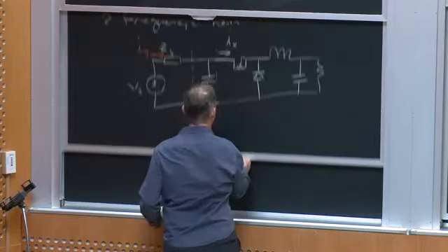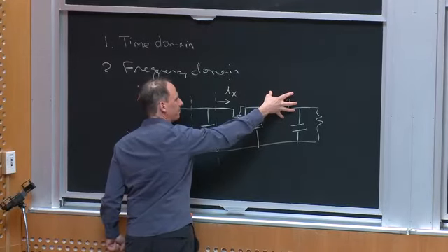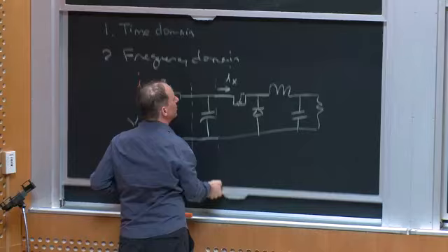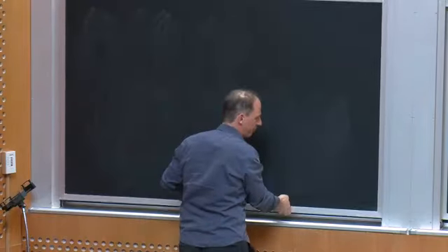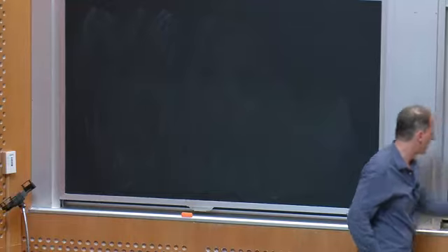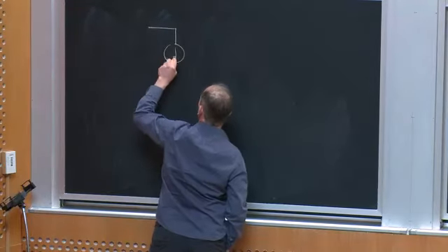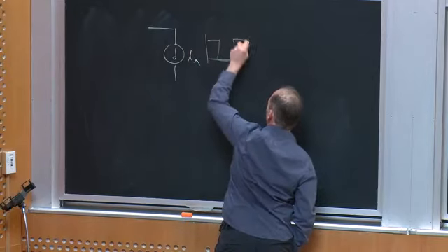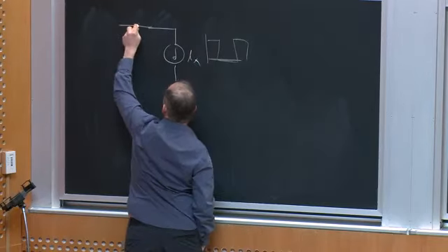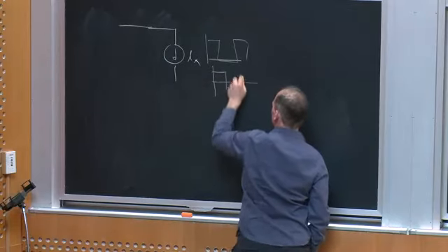Maybe the easiest thing for me to do is say, let me pretend this is a constant current inductor, right? I'm not going to worry about the inductor ripple. And a simplified model for this would be something like this. I'd have some current Ix, which is some square wave, right? And then maybe I would only care about Ix tilde, the AC component of that.